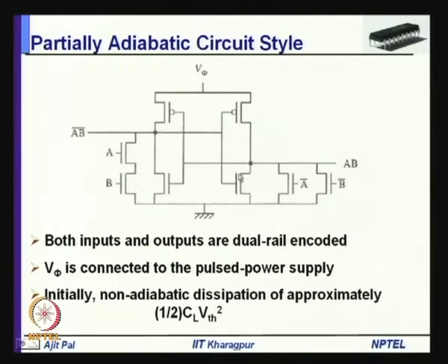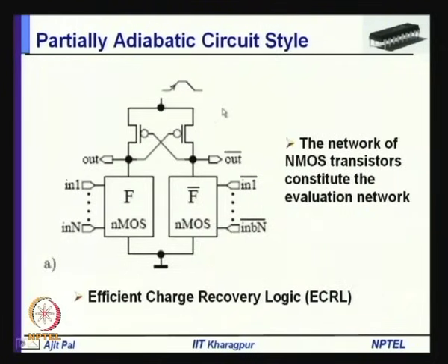So, this happens, and this non-adiabatic dissipation takes place in this particular circuit. Now, there are several adiabatic logic circuit families. I shall briefly mention them. One is a partially adiabatic circuit style known as ECRL, energy charge recovery logic.